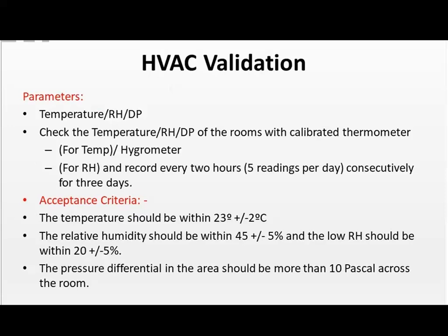So they're going to be in there carrying out a HEPA filter qualification for a few days, quite some time, and typically this is done when manufacturing has shut down for a few days. A lot of plants will shut down manufacturing around the 4th of July, some around Thanksgiving and Christmas. So your HVAC requalifications can be done during these times.